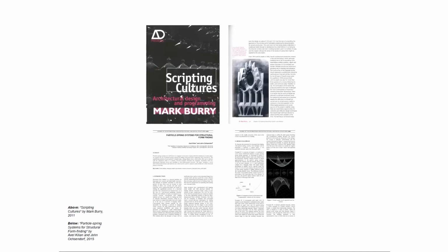So the idea is that you can create these catenary shapes and use dynamic relaxation, and you can apply additional external forces to them, specifically gravity. Then you can get these hanging chain models, same as Gaudí in Sagrada Familia. And if you invert them, you get compression-only surfaces. They described this in this paper in 2015.